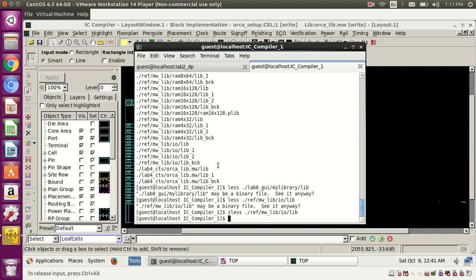In ICC2, there aren't that many settings. I did this long ago, man. There are many scripts. I worked on clock gating almost 2-3 years back, so I don't remember the settings, but we don't do anything, the tool does it. While doing clock gating we just need to know these are the clock gating cells. That means the master name will be there, so whenever we see it in that report, based on that master name you should say okay, this is a clock gater cell.